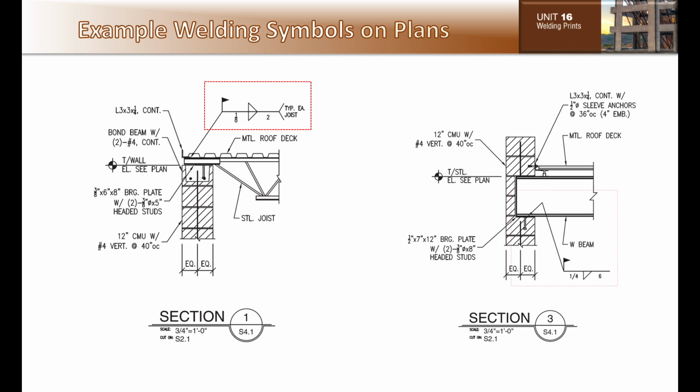This steel beam detail also has a field weld to the embedded plate. The weld is a 1/4 inch fillet weld by 6 inches in length.